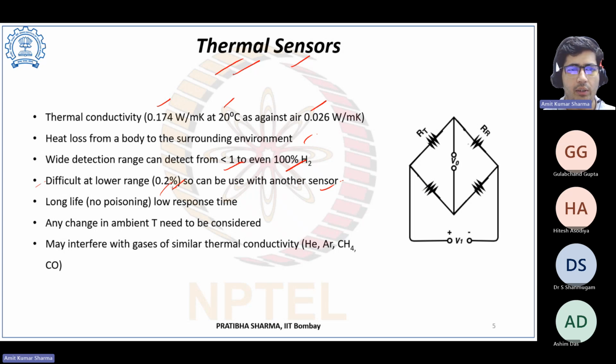Long life, no poisoning, low response time. Any change in the ambient temperature needs to be considered, because it works on thermal conductivity and is calibrated at a fixed ambient temperature. If there is a change in your ambient temperature conditions, then you need to recalibrate it. So you have to consider the ambient conditions also.